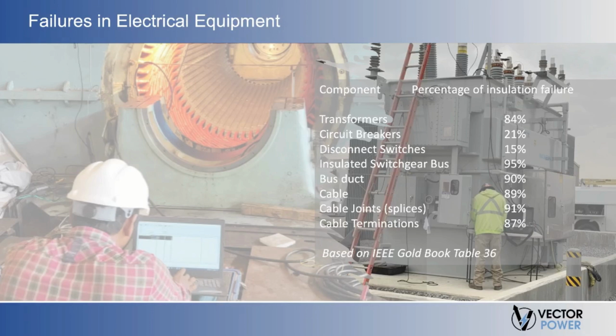Insulation may be deteriorating, however, the equipment may not fail for some time. Although this condition presents a serious hazard, if deteriorated insulation is detected before failure, it can often be reconditioned instead of being replaced. This allows corrective action to be taken during a planned outage before extensive equipment damage results from an insulation failure.